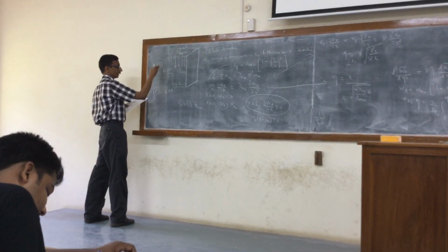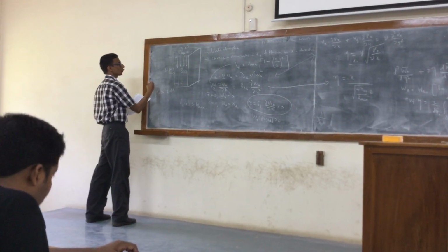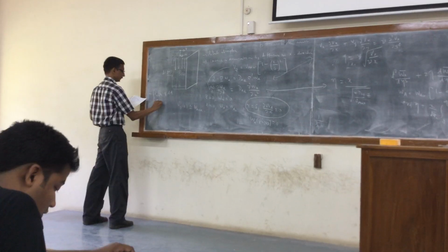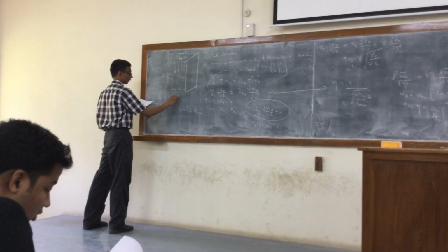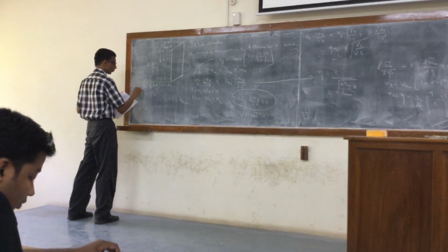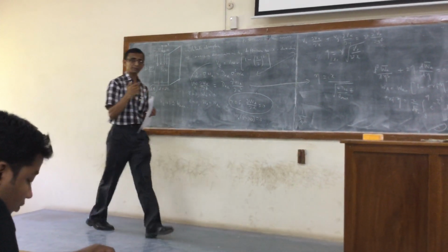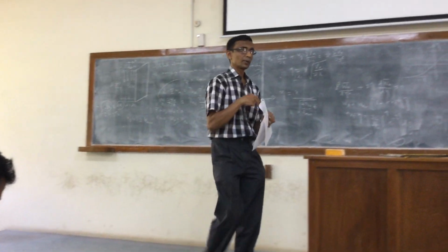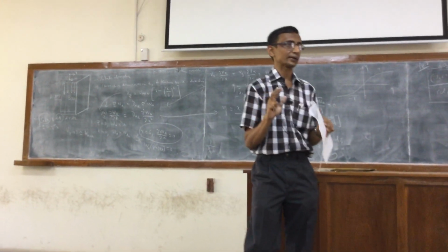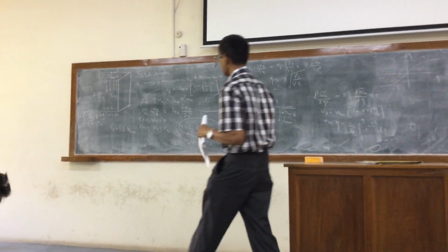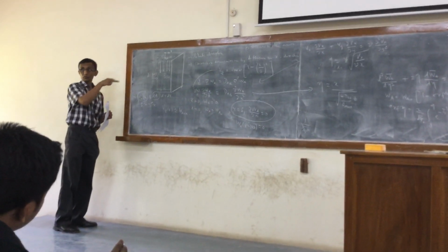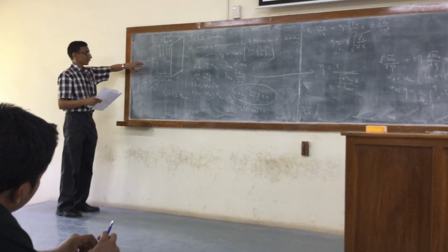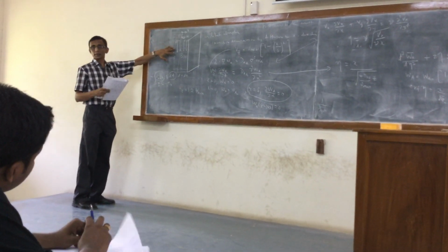So across the interface, n is clearly the outward normal, which would be minus e_x, times dy dz. So the whole point is how he calculates rho_A v_A. Look at Bird, Stewart and Lightfoot. We are not calculating the velocities directly. Now rho_A v_A, what I want is the x component. You have to understand that the diffusion is dominant in the x direction.